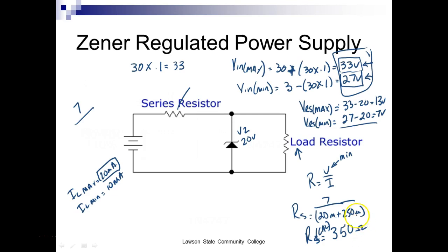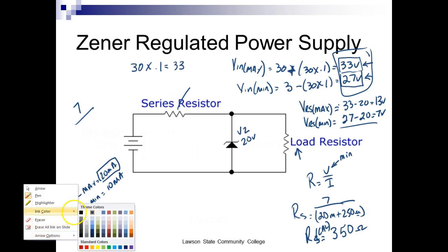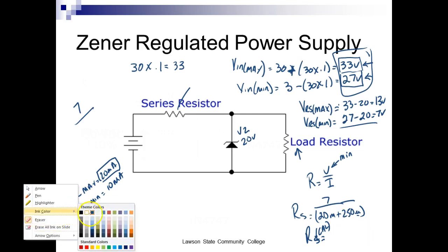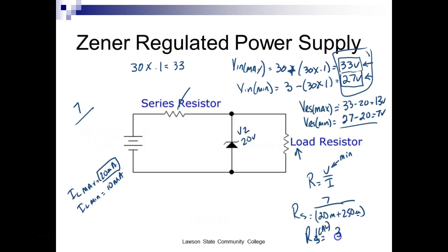250 micro, yeah. So it'd be 345. Three and what? 345. Okay, that's calculated. That's not what we're going to use. So what's the next standard? What's the next standard value below 330? So I'm going to take 330. I'm going to multiply it by 1.05.